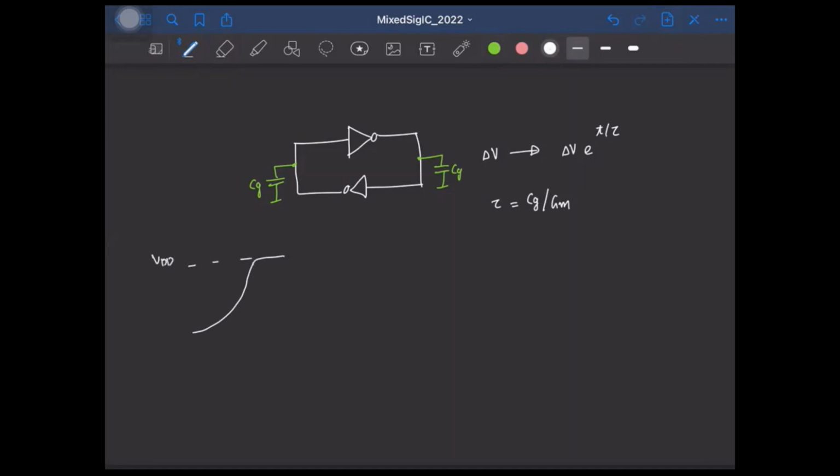And of course from this we can clearly see that the gain of this regenerative latch is e^(t/tau). So if say the time available for comparison is some Ts/2, at this point, then the gain is simply e^(Ts/2tau), right? So let me write this to be the gain.